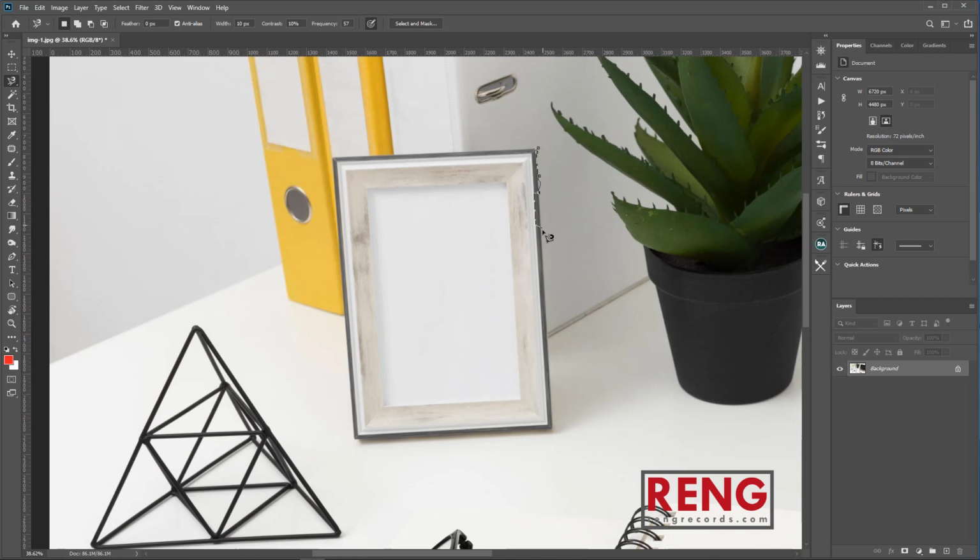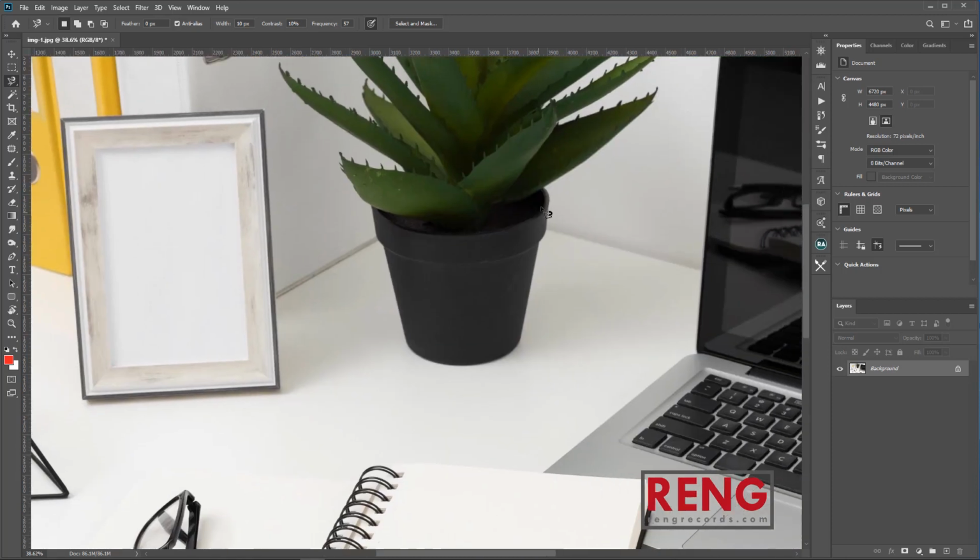Now, move the mouse around the desired area along the color border. In this case, the points will automatically be placed on the border. To add points, you can also click yourself, and to remove one, you can press the delete key on the keyboard at the wrongly selected point. Number 4. When you have completely traced the desired area with the mouse, you can complete the selection by double-clicking the left mouse button. With this, the starting point is attached to the end of the last point, and the desired area becomes selected.